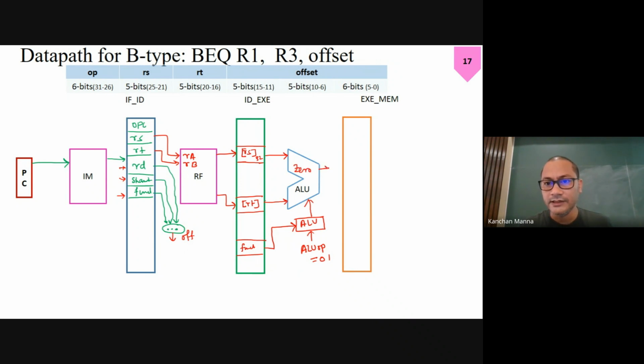A zero flag is here. Same way, we have to take the value after the stage register, because this is purely combinational and there can be change. So here also we have to allocate a 1 bit register, let's say for zero. What could be the size here? Why 32? This is a zero flag.